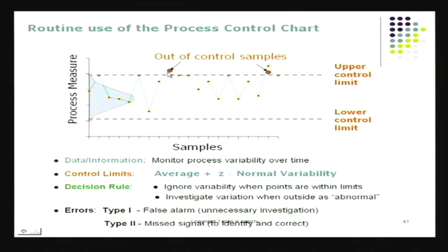Don't second guess. The moment the chart has gone beyond control limit, stop the process and go to something that is called the reaction plan, which is what you construct using the cause and effect diagrams and so on. But then go through your full list of checklists, and check everything about that machine, just to make sure that you will not end up thinking everything is in control and producing products that are off spec.